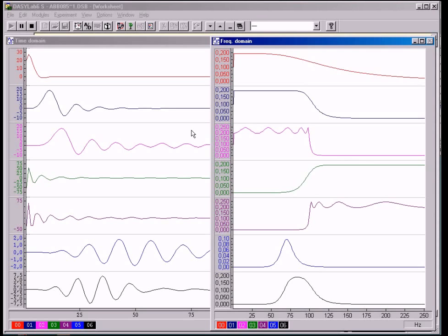The importance of the delta pulse as a test signal is based on the fact that the Fourier transformation of the pulse response already represents the frequency response. That means the transfer function of the system tested.